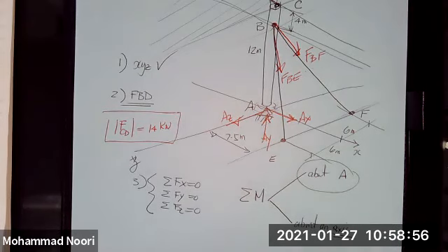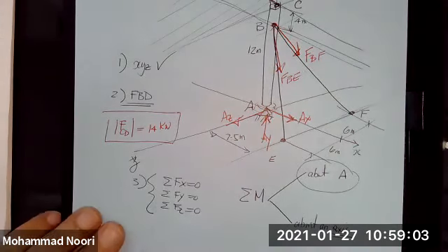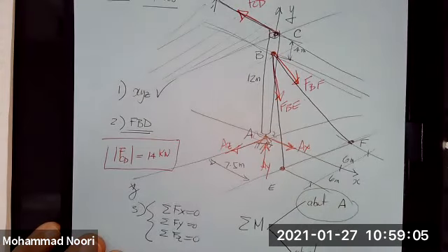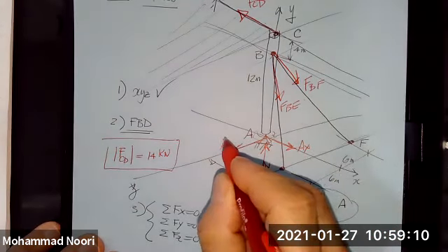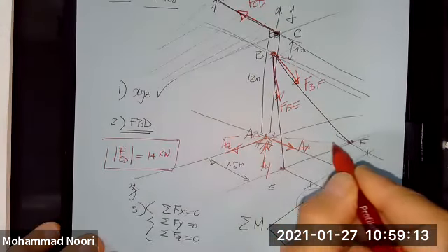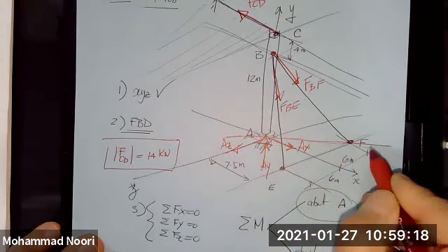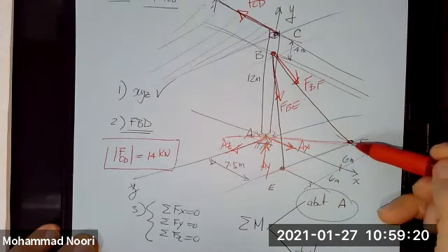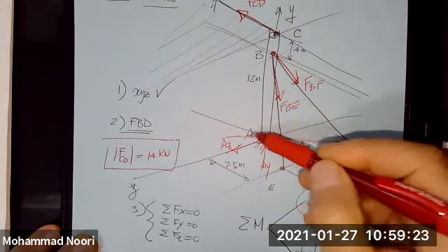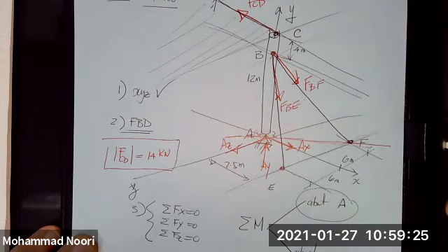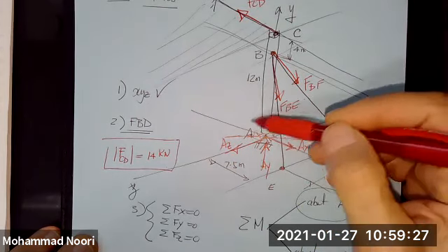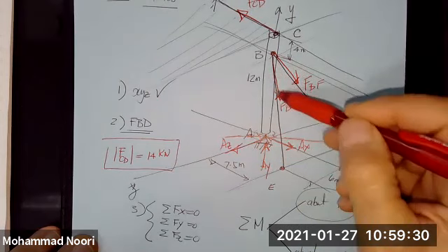And I see that, ironically, it is quite interesting. If I look close, I can see, in fact, such an axis. If I take summation of moments about this axis, this force intersects with that axis. These three do. The only unknown I have that does not intersect is only this force.